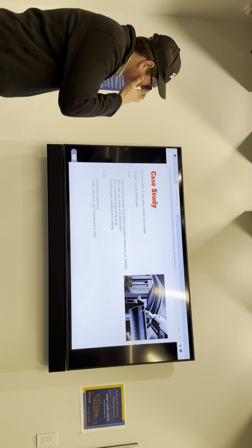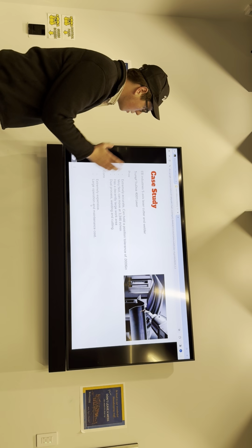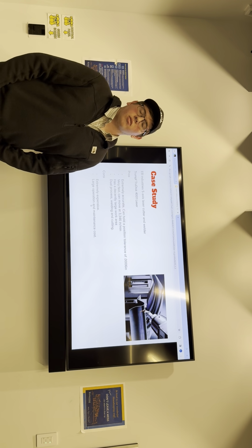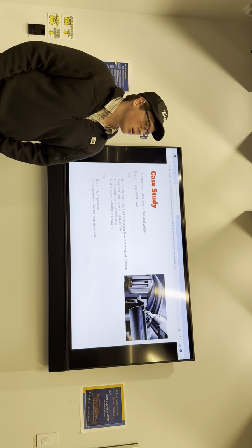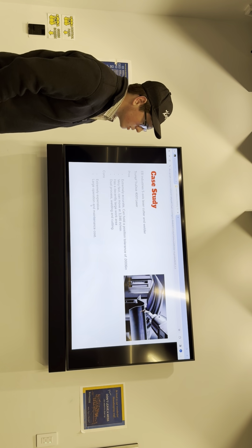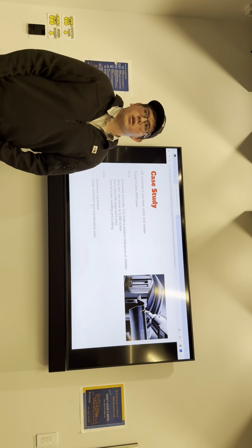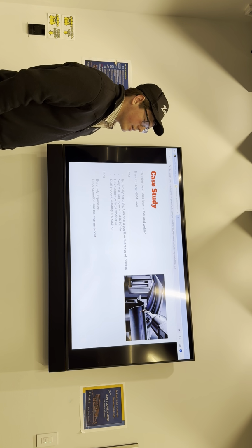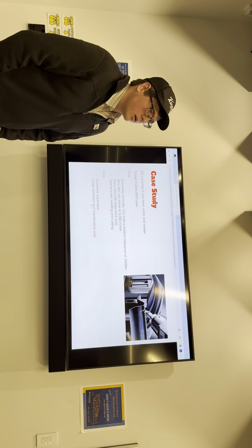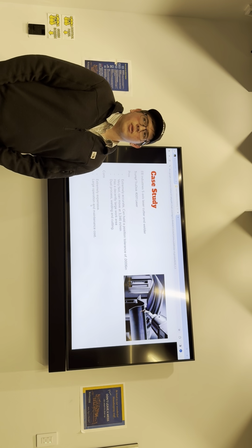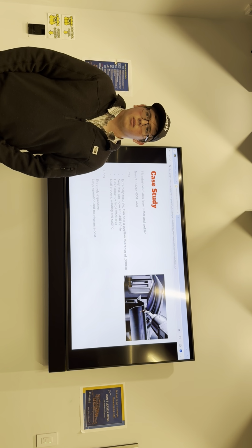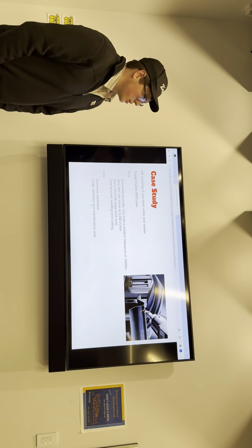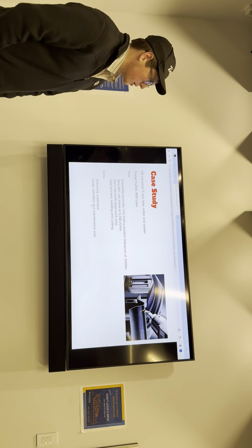So some of the pros and cons of this machine: the pros, this thing is super accurate. It can hold 6/10,000ths of an inch in true position, which is insane when it comes to a 5-axis machine. Most of the mills and stuff that I work with in my co-op cannot do that. We're lucky to hold 2/1000ths. So that was a big deal to me on this machine.